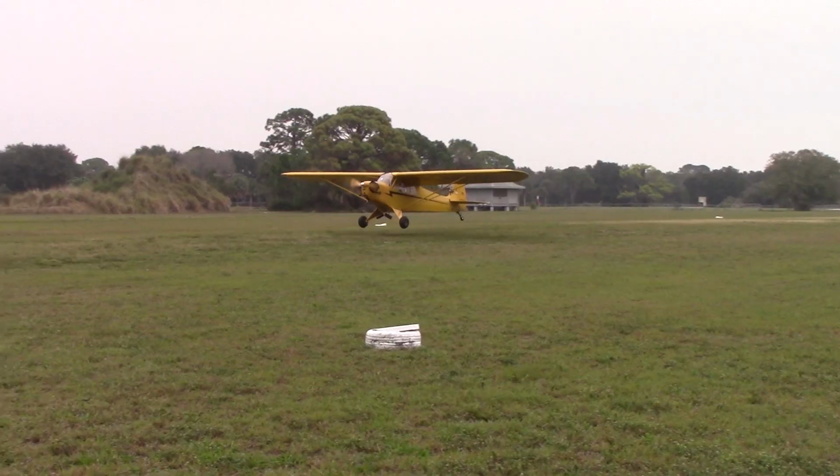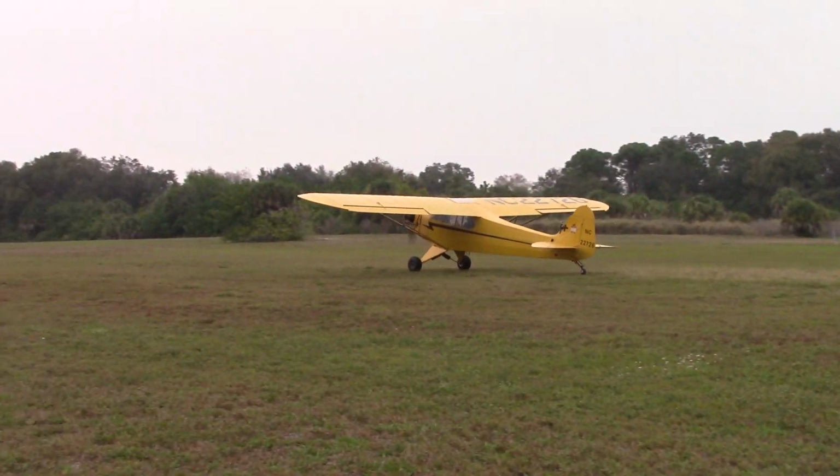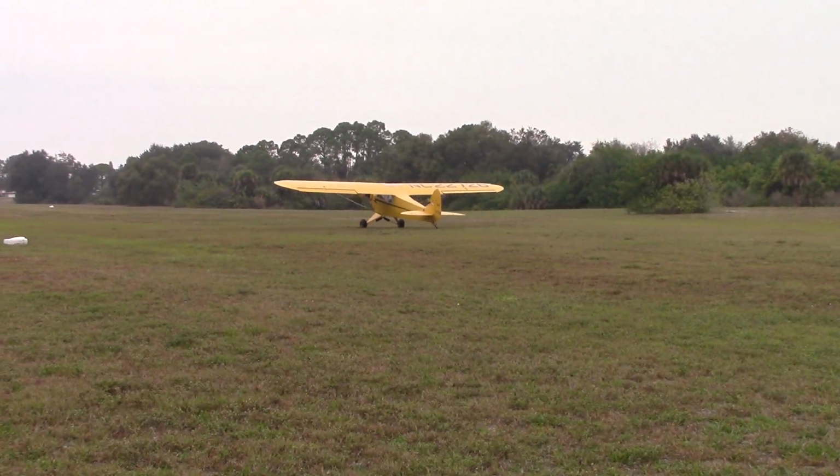You know, if you've got much flight time at all, you have probably noticed that a good landing is usually preceded by a good approach. But a good approach doesn't necessarily assure a good landing. And I found that in tail draggers like this Cub, I really need to be exactly on speed through most of the approach in order to get a good 3-point touchdown, and even then, some landings are better than others.